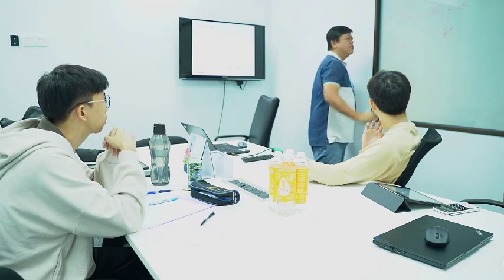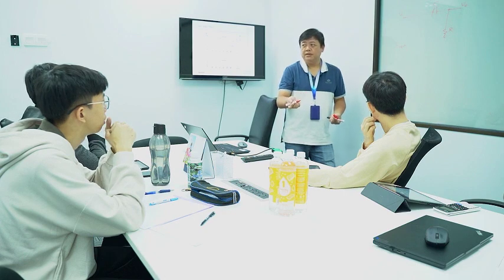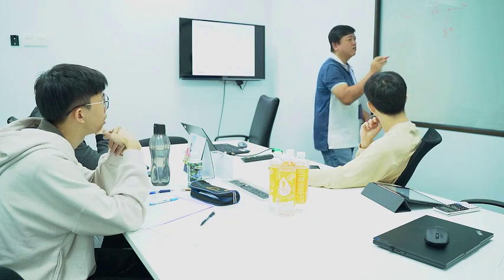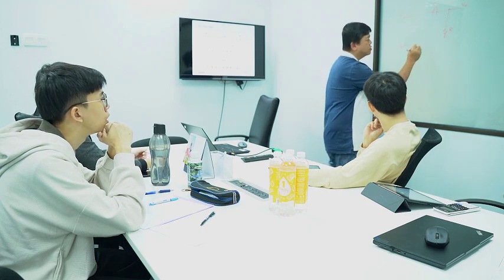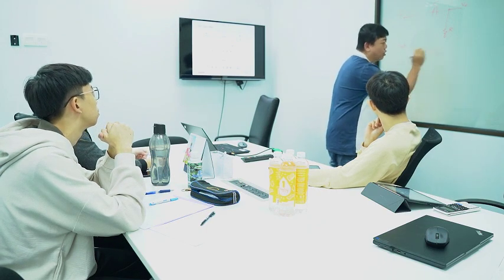because this gain is very sensitive. It can be power gain. Power gain is in your S parameter in RF, right? It can be a voltage gain, or it can be a current gain. Current gain means that input is current, output can be voltage or current. For example, a transimpedance amplifier: your input is a current, output is a voltage. That one becomes dB ohm. It's very different. Example for a current input amplifier is the common gate amplifier. Input is current, so your output becomes voltage, so your unit actually is dB ohm. Very different.